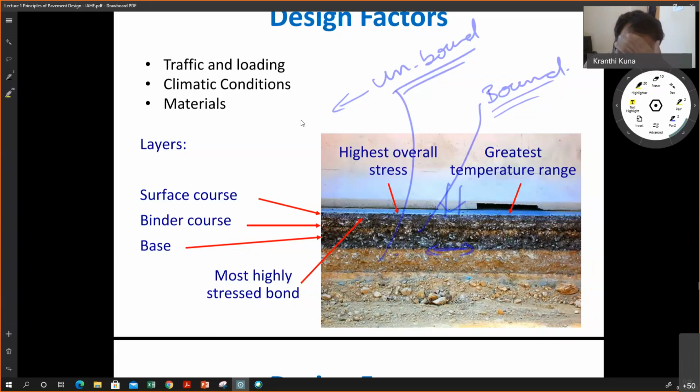So what are the things we have to consider? Like the tensile strain here, and obviously as part of pavement design, these undergo different climatic conditions. For example, the temperature at this location will be much more than the temperature somewhere here, depending on the temperatures and also what type of material you have. An asphalt material, an unbound material, and the subgrade. We have to consider all these.